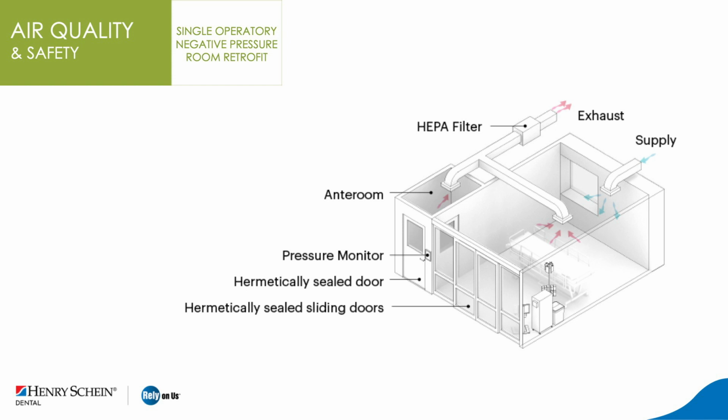Now, you know, it won't be 100%. Generally, it's going to be anywhere from 10 to 40%. So the vast majority of the air in the space is recirculated air that's passed through a HEPA filter, but there is a fresh air fraction or an outside air fraction of 10 to 40% that's actually being introduced.